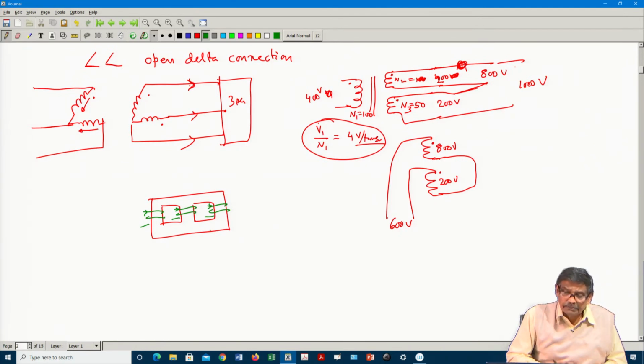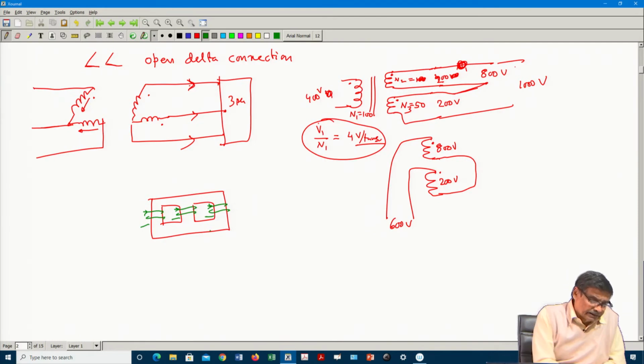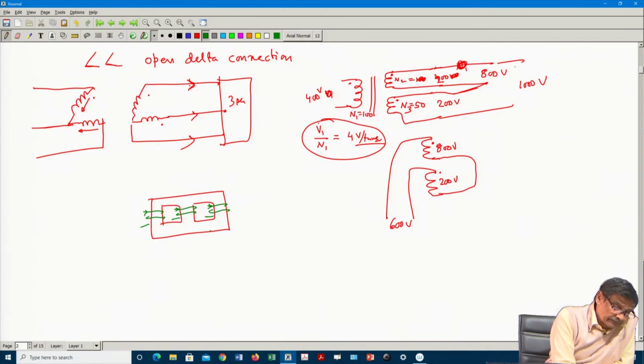So, in a rotating machine, that was one of the most important contributions of Nikola Tesla. He told that if you have distributed windings, 3 phase machines, excited with 3 phase balanced current, then a rotating magnetic field will result, and based on that you can make an induction machine and also a synchronous machine, because the armature winding of a synchronous machine is also balanced 3 phase. Anyway, I think this is about that question.